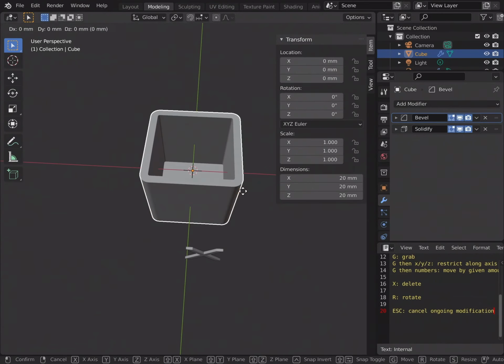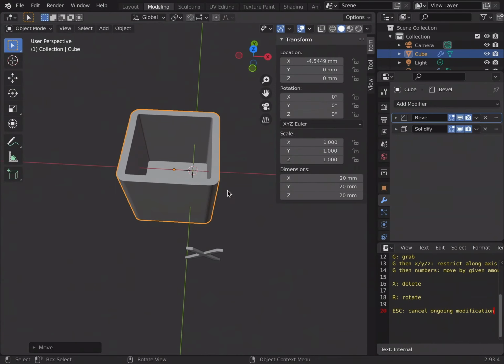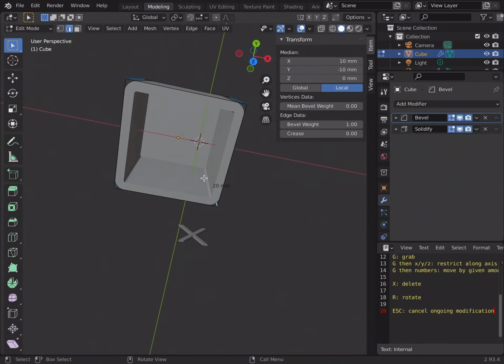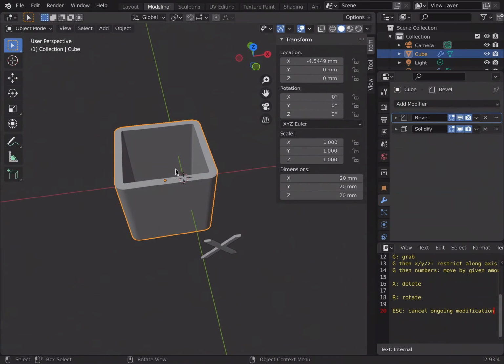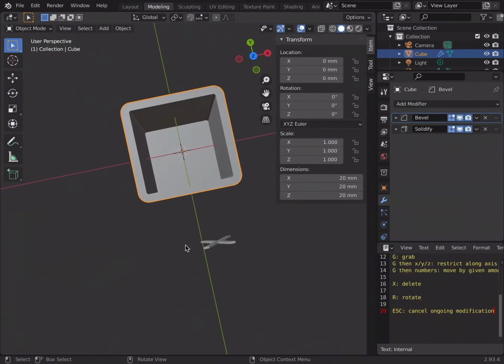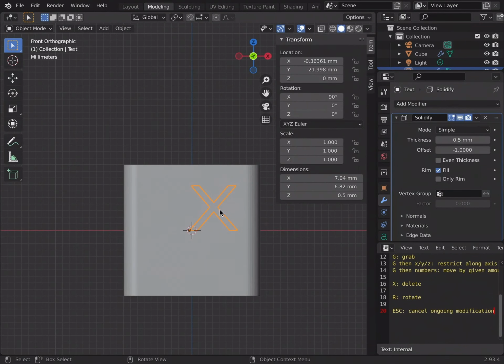And so if I move this a little bit to the left, go back into edit mode, we can see that the location of this axis here is still at x10, y -10. If I move it further to the right, this is still the same. So those coordinates during edit mode are all in relation to the object's origin. And when I'm in object mode, everything is in relation to the world origin, which I can set back to 0 here manually again. So if we want to center it, we need to make sure that the object's origin is in the center.